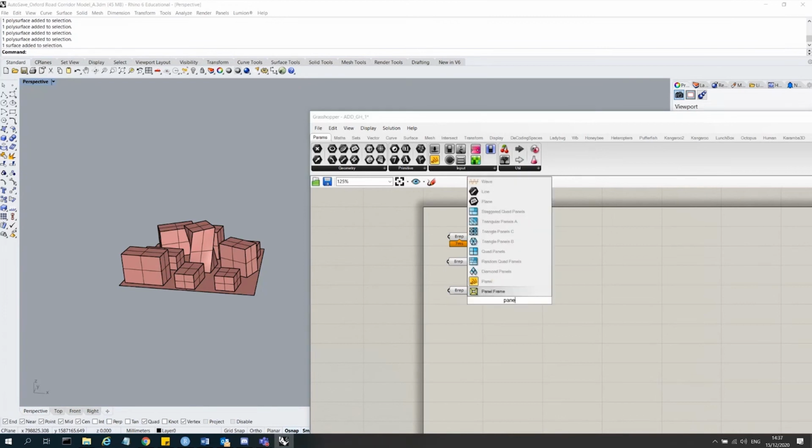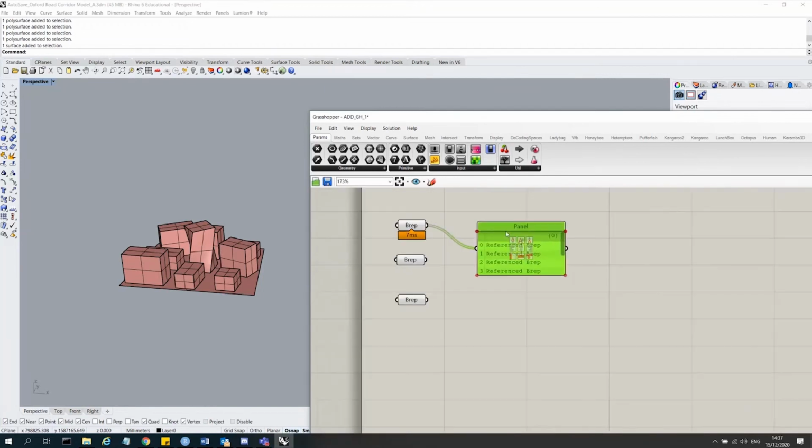A trick to use always in Grasshopper is use this panel. So this is a way for you to know what's going on. So whenever you connect, so if I'm connecting this over here, you can see it's telling me there are 7 geometries that you've imported in. And you can see this is called a list. So list in index 0. So lists in Grasshopper and Python language, they always start with 0. Think of it as a kind of a ground floor, right? So it's always represented as 0. And then the first floor or whatever, but you can see.